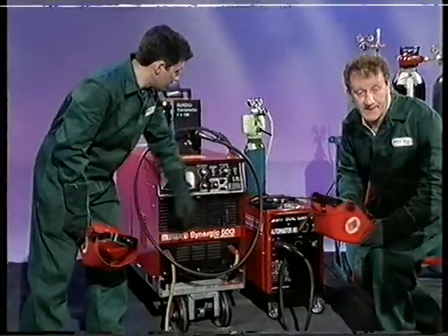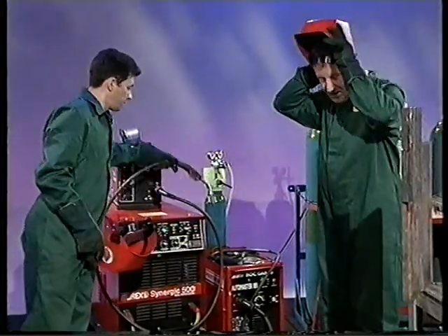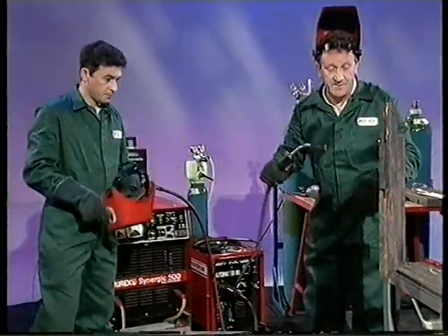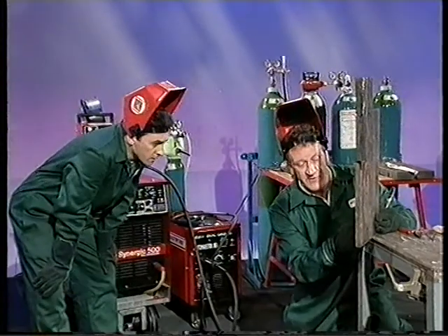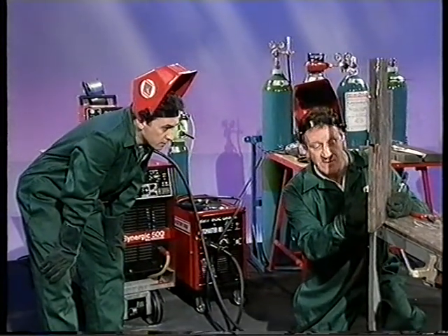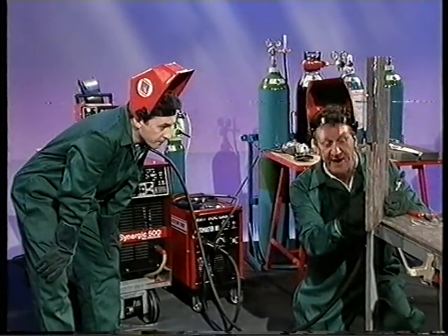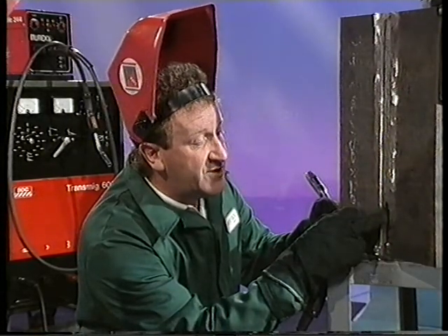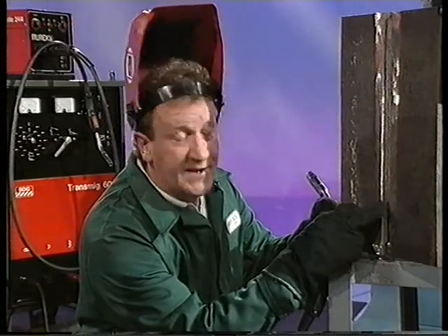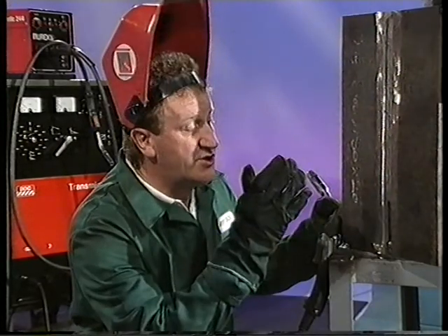Okay, fine, so it's just power on really, isn't it now? Put the power on, yeah. There we are. I set the conditions earlier and put a small run in here, and I think you can see on the root run here, at the end where I've stopped, I've had to grind the crater out. This is called feathering the crater. This enables me that when I start, I should get reasonably good pickup on the back of the penetration bead so that I have an even penetration bead.